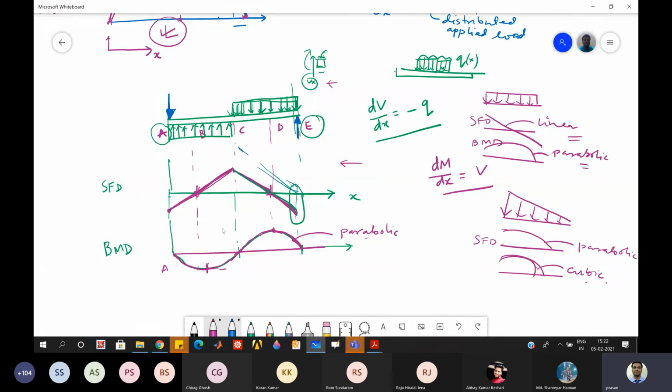Now, if you look from top down or bottom up, the shear force diagram is anti-symmetric kind of thing, so the loading also is an anti-symmetric loading. If the bending moment is anti-symmetric, then the loading will also become anti-symmetric.